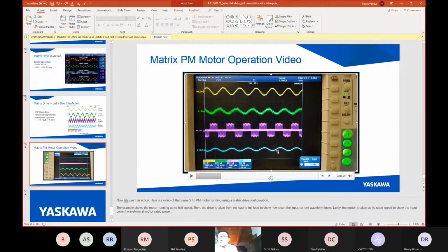What applications would require that? Most significantly, any long lead length applications, and especially long lead applications on non-NEMA motors, such as the downhole submersible pumps, which is a monster industry in the oil and water markets. Lots of downhole submersible pump motors. In the oil patch, down to 10,000 feet. In the water industry, 1,000 feet.